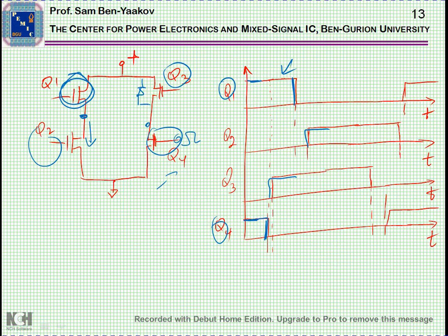And as you can see, there's some shift of this signal, and this is why it's called a phase shifted PWM converter. Now there are chips, of course, control chips that will generate this waveform automatically. You don't have to worry too much about it. You just have to choose the proper IC controller to do the job.